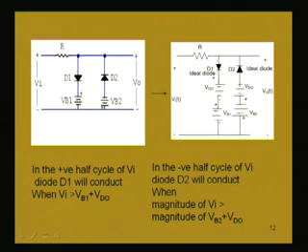Now, let us consider a positive half cycle of the input voltage, that is positive half cycle when this point is at a higher, positive potential than this point. So, when it is positive, you see this Vb1 and Vb2 are connected in such a fashion that they are already reverse biasing these diodes. That means, this Vb1 positive is connected to N, here negative is connected to P, that means both are connected in such a way that both the diodes are already reverse biased.